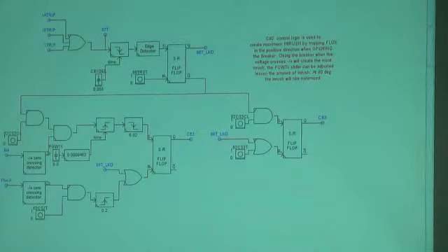The circuit breaker control here is used to create a maximum inrush by trapping flux in the positive going direction when you open the breaker. So that when we close, we create a worst possible inrush.